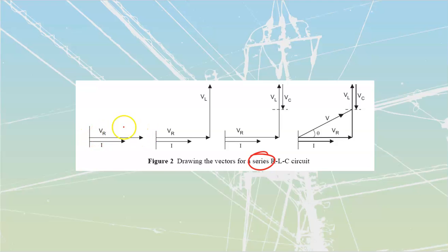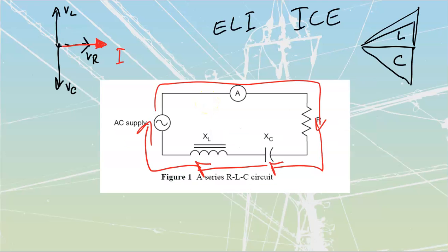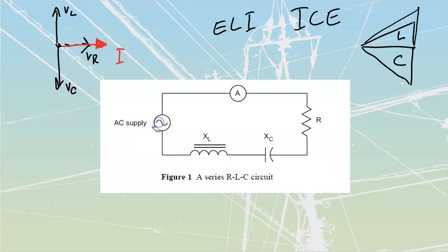I see I've got my resistive voltage. I see I have got my inductive voltage. What they're doing right now is they're saying, I've got this circuit over here. Because it's a series circuit, I'm just going to step back three steps over here because they don't really lay out what they're doing inside of here. But because it's a series circuit, I know that it has to satisfy Kirchhoff's voltage law, KVL, which is that the sum of all voltage drops is going to equal my source voltage.